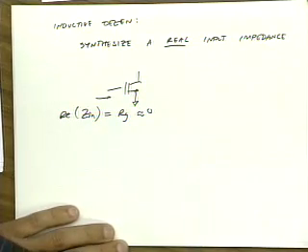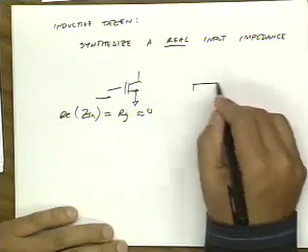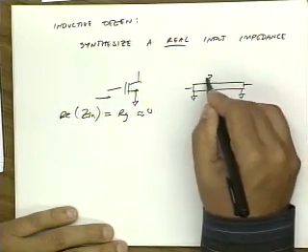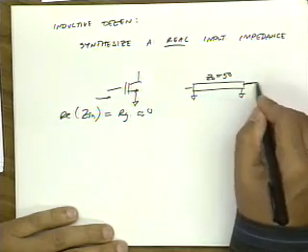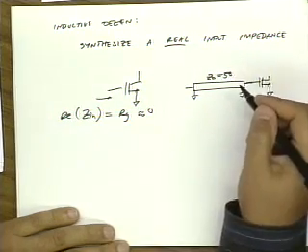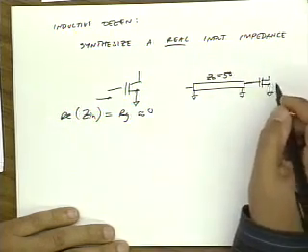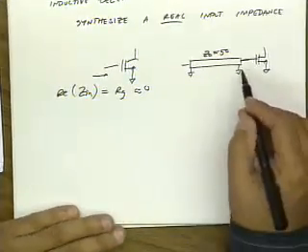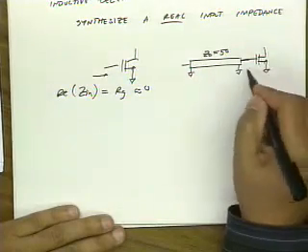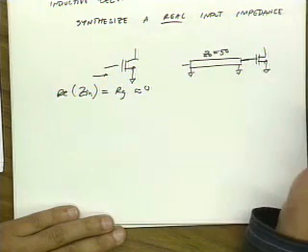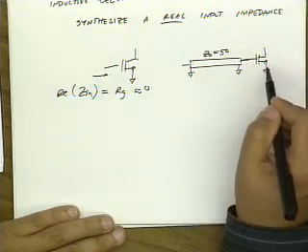And let's say I want to drive this with a 50 ohm source resistance, right? Let's say I have a cable or a transmission line which has a Z0 of 50 ohms, and I want my transistor to terminate this with 50 ohms. Well, that's pretty hard to do with a transistor. A transistor on its own is going to look like a capacitive termination. Another way to look at it is if I want to extract the maximum power gain of this transistor, I want to drive it with a source impedance which is the complex conjugate of the input impedance.